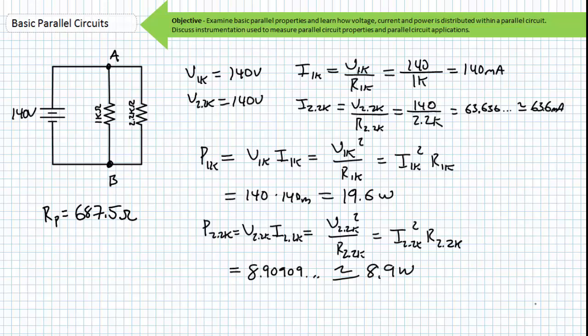I'll let you in on a little secret. Very rarely, if ever, do you need to solve for the total resistance of a parallel combination of elements if you can simplify a complex circuit to a purely parallel relationship. You may have to solve for the resistance of a parallel combination inside the complex circuit. However, once you reach the base level of simplification as a pure parallel circuit, it's often better to simply resort to the most fundamental of parallel properties. Voltage across elements hooked in parallel is the same. You'll appreciate this time-saving step when we enter series parallel circuit analysis.